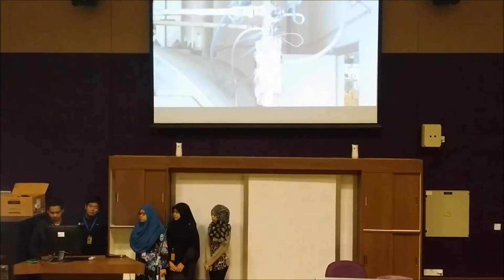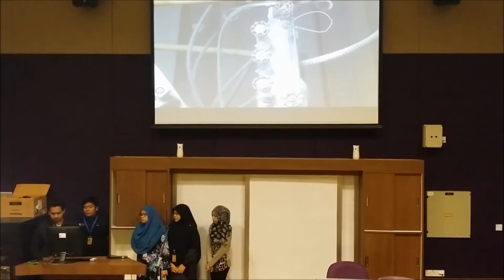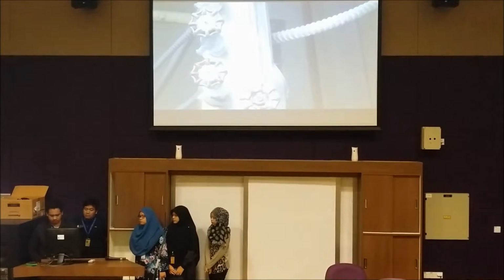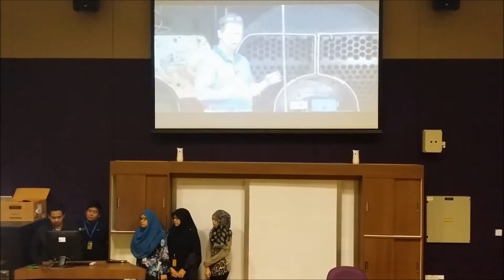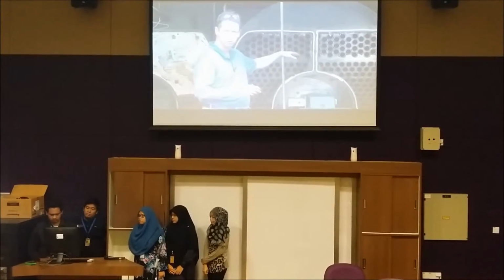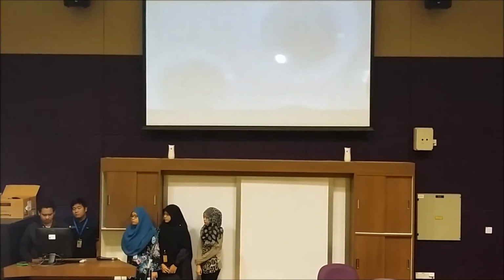But we've got safeties on the boiler. The low water fuel cutouts are designed to shut down the burner of the boiler before the water level gets to a specified area. The key is if the water level drops below, for example in here it drops below the tube surfaces, now we've got flame going through the tubes, it can overheat the metal of the tubes, and we get things like melting of the tubes, and just bad things happen with the boiler when we get low water.